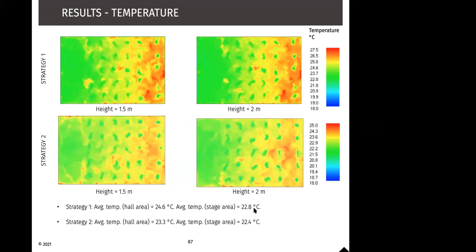So you can utilize CFD to understand if there is any heat accumulation happening, and if there are any zones which you have detected as hotspots, you can rectify the problem by either providing more CFM of supply, or by providing more return air risers, or any sort of system to remove the hotspots.